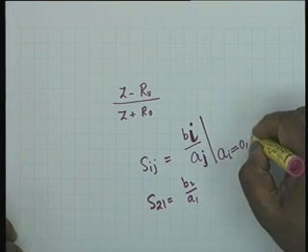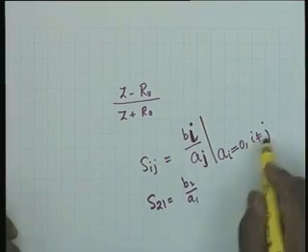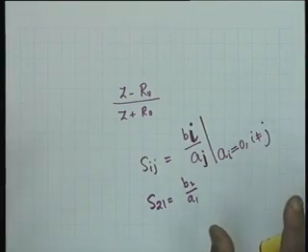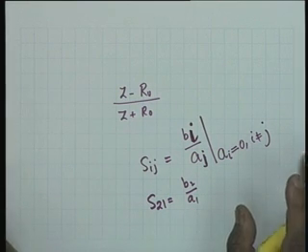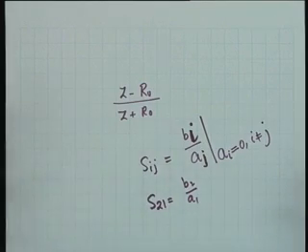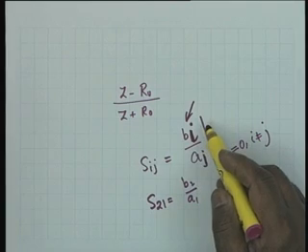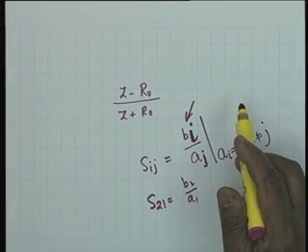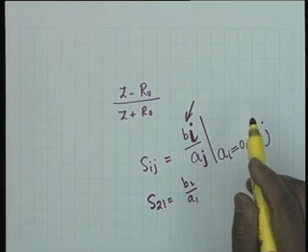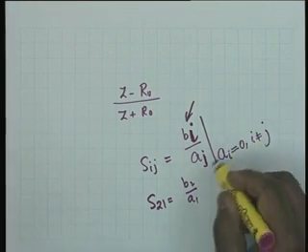Agreed. Now here all other Ai's are 0, we are assuming a multiport, more than 2, which also shows that scattering parameter description is equally good for more than 2 ports. It could be a large number of ports, doesn't matter. But the point that I wanted you to notice is that numerator is a reflected parameter. Reflected parameter may or may not exist. Alright? If it doesn't exist, it means that the reflected variable is 0. But what hurts it is if an Aj is 0. How can an Aj be 0?